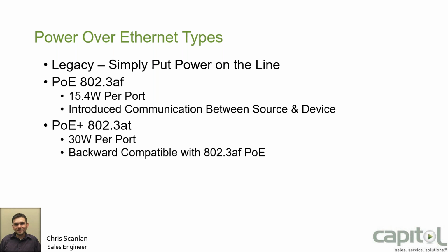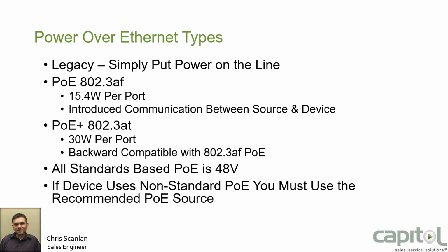You really want to keep in mind what devices you're powering, okay? All these are based on standard 48 volts. Some devices actually say they use PoE, but they're not using 48 volts. If that is the case, you cannot use a PoE switch, okay? You need to use the supplied PoE injector that comes with it, okay?